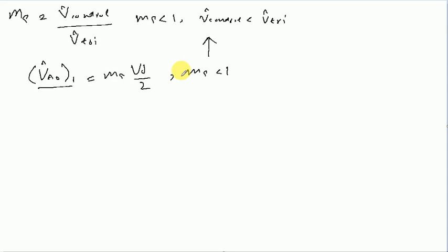The advantage is that the amplitude modulation ratio being less than 1 pushes the harmonics into a very high frequency range around the switching frequency, and also its multiples, so that makes the filtering relatively easier. The discussion that we are having now is mentioned in the book under the name of overmodulation. So if you want to read the relevant material, you can read it from over there.